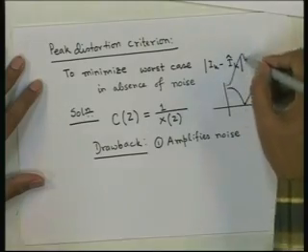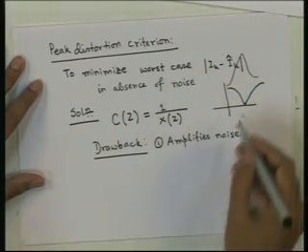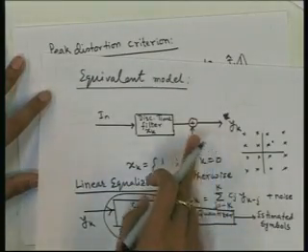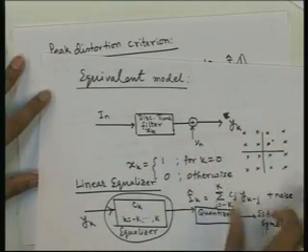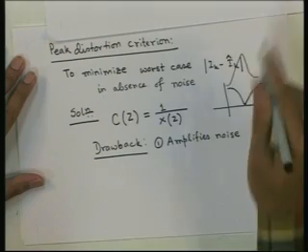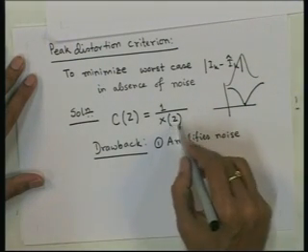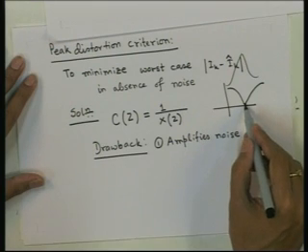So, it will have something like this, and as a result the noise which is introduced here and which is going through that equalizer filter will be amplified very much in this part, wherever this filter X z has very high attenuation.